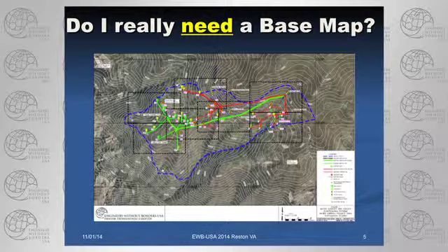Thank you very much. Some features that I especially like about this one: the community boundary is actually shown. This one has the system layout over it, but it clearly shows the topography and the satellite imagery. There's a clear legend that shows what all the different features are, all the key buildings, all the roads, pathways, and everything that applies. And there is a scale. Yes, there is. Do you see it? Okay. And a north arrow. Yes. All these great features that are so often missed. Basically, through this presentation, you're going to learn how to make a beautiful map like that. So that's the baseline map that any water system needs.